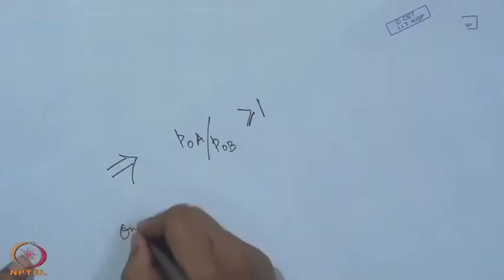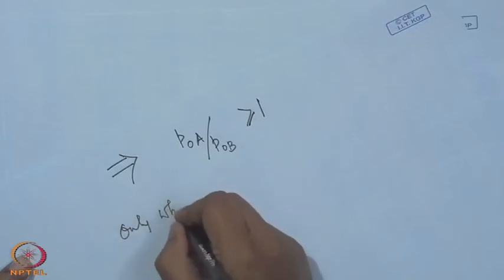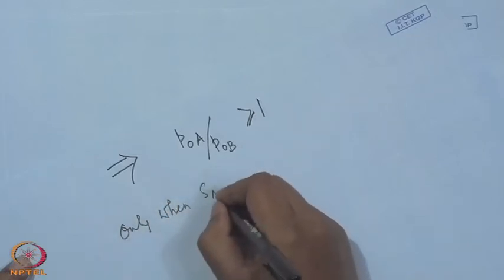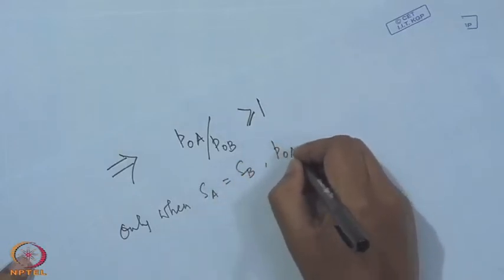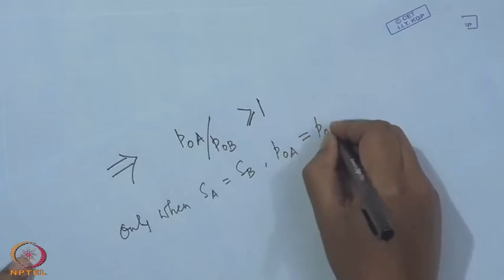Only in such isentropic processes does the total pressure also remain constant. The reservoir conditions or stagnation conditions are also called total conditions, and these terms are used to define conditions at any point in the flow.